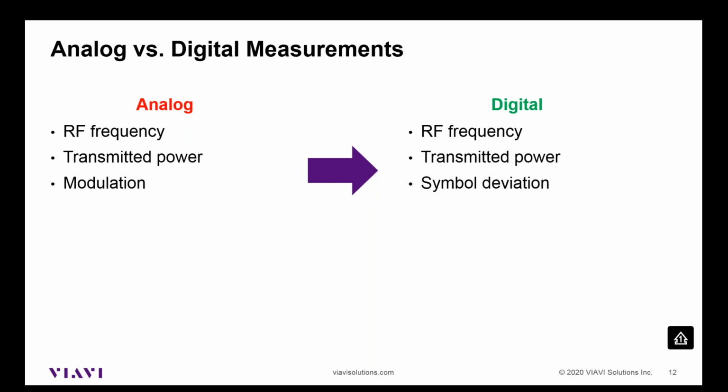So once again, if we look at an apples to apples comparison there, for the same proper alignment of a radio, analog versus digital, the digital is going to outperform the analog radio in terms of signal quality. Again, if you have a poorly aligned digital radio, that's not necessarily true, and it may look like the digital radio performs worse. So with digital radio, the alignment is critical. Again, frequency and symbol deviation are the two biggest things that affect that. And if those are not aligned properly and measured properly, you run the risk of having a degraded performance.